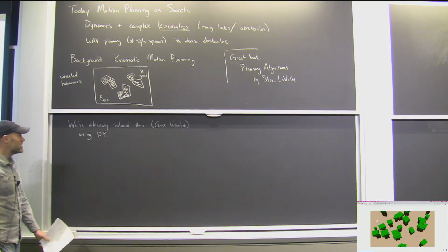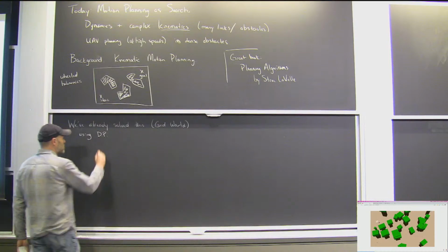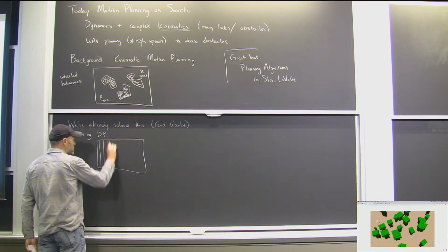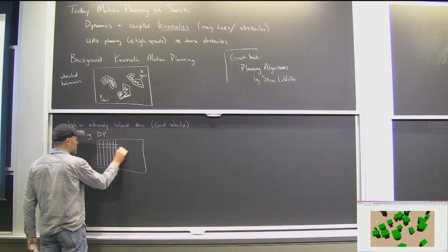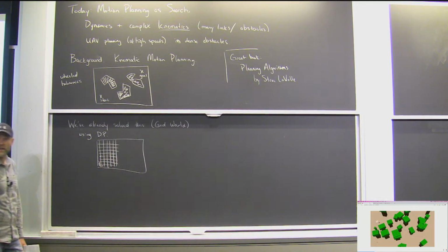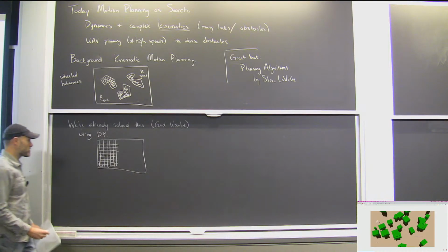The strategy that we gave you back then, right, was to go ahead and just discretize the space, make a small graph on top of the space, and then write our dynamics on the graph, and we could solve a value iteration problem.